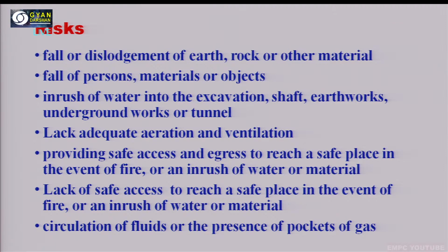Then there is providing safe access or egress to reach a safe place in the event of any accident. What type of accident? If there is a fire, an inflow of water, or the falling or dislodgement of some material. In these cases, what comes to mind first is to rush to some safer place. If we are working in a deep cut or in a tunnel, then it is very difficult to get safe access because the space is limited there.